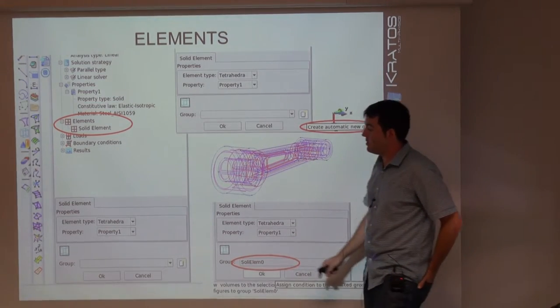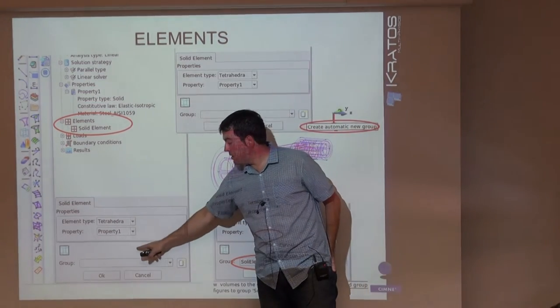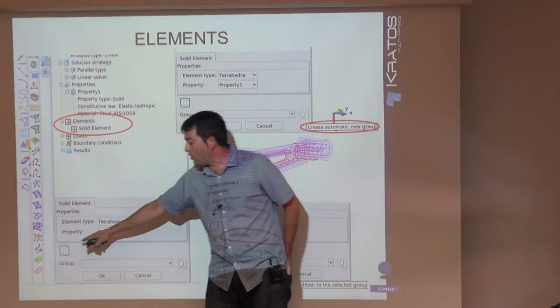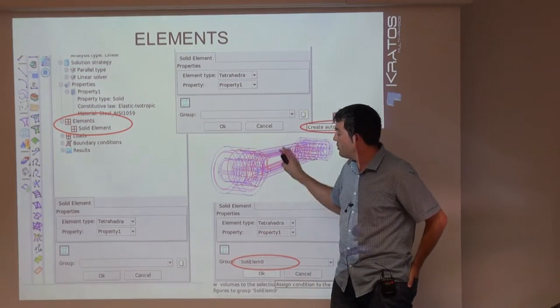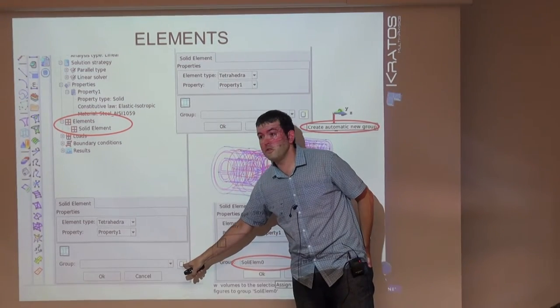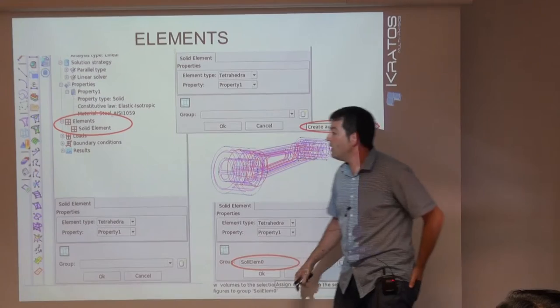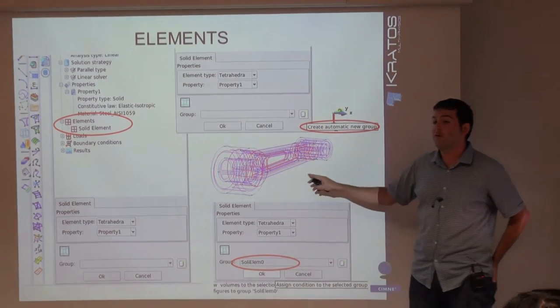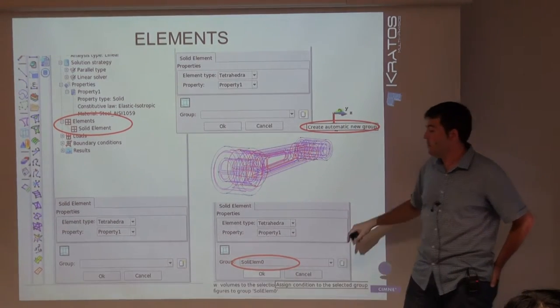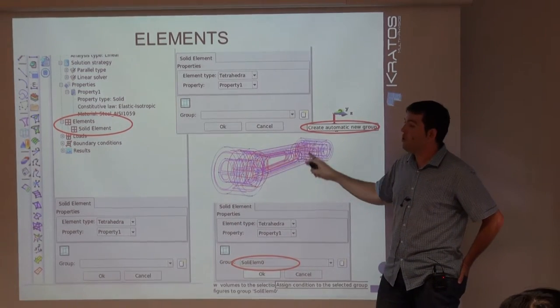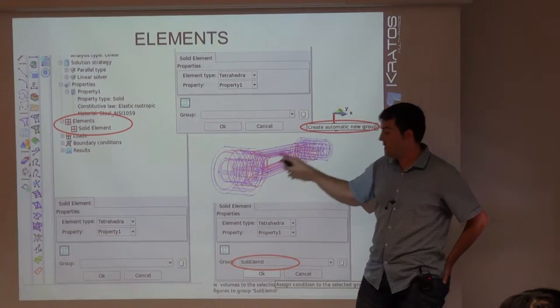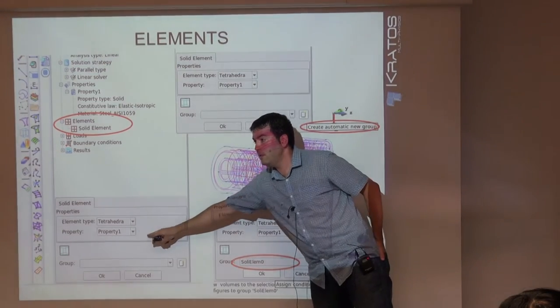The first one is, let's assign the element to volume. We are in 3D, right? And let's create just the group to assign this element. So we push on this icon, and we select the group. And this is the thing that I have done in this example, right?